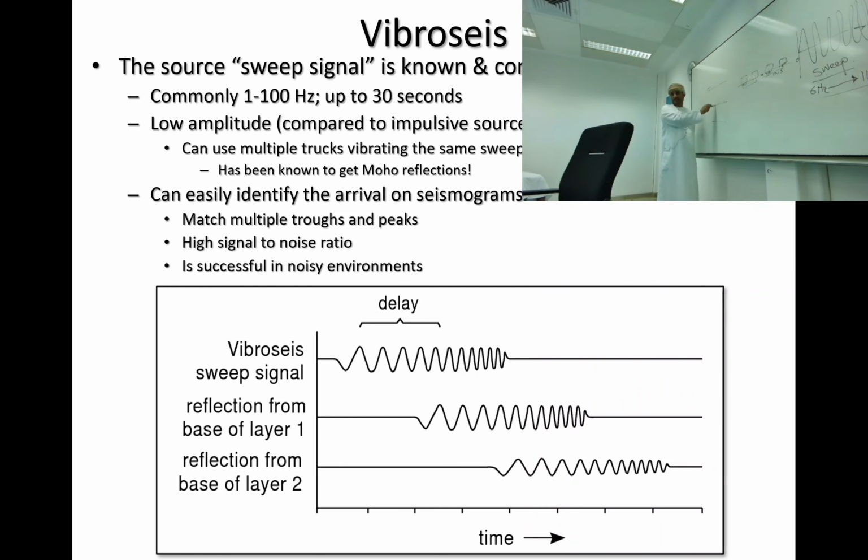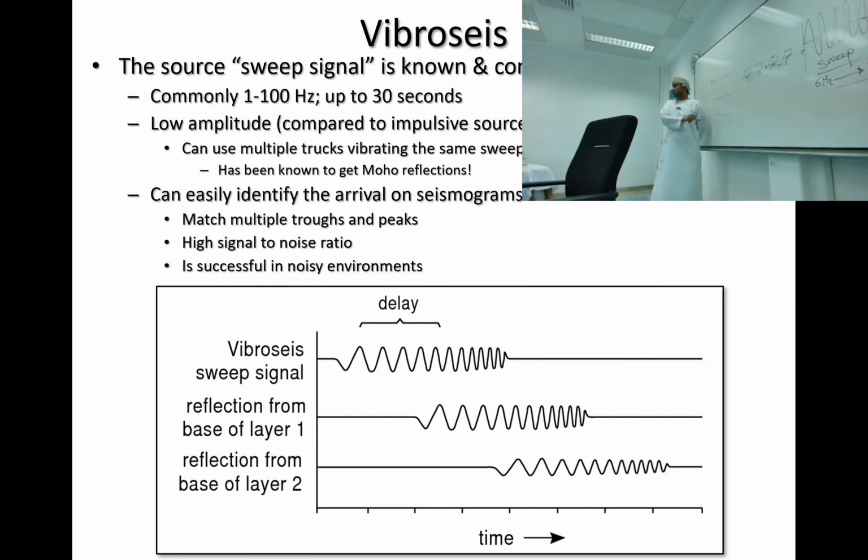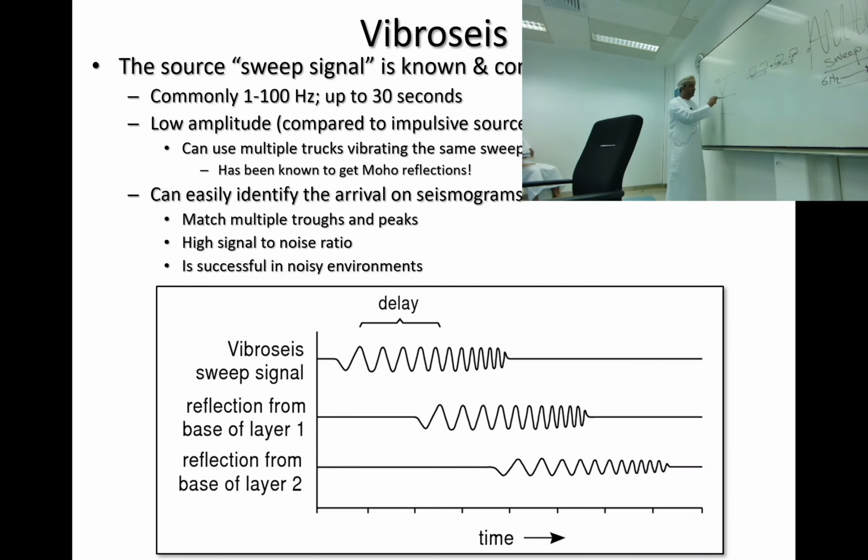All of this signal goes as a train of waves into the ground. Once they hit this interface, what happens to them? They reflect back, am I right? And the angle of incidence is equal to the angle of reflection, based on Snell's law and the Fermat principle. So once it goes back, this geophone will record a train of signal.